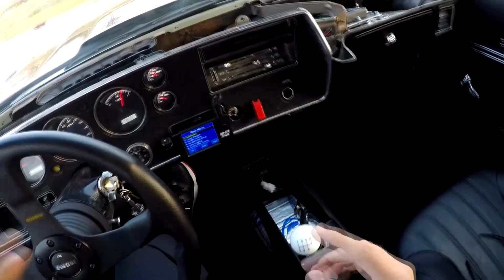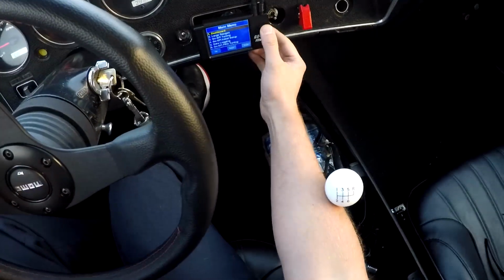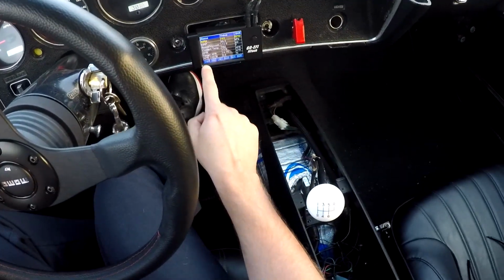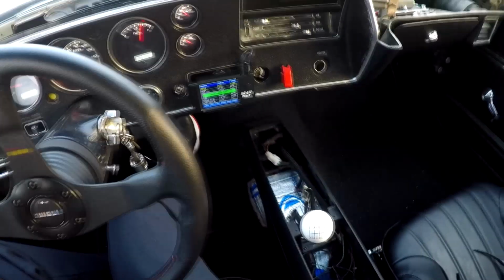It has been requested that I make a video on how to data log your FiTech or otherwise similar fuel injection system. So in this video I'm going to show you how to do it, how to read it, and the value of that information. So stay tuned. To start your log, you go to your dashboard and all you have to do is say log on, and now you're logging.